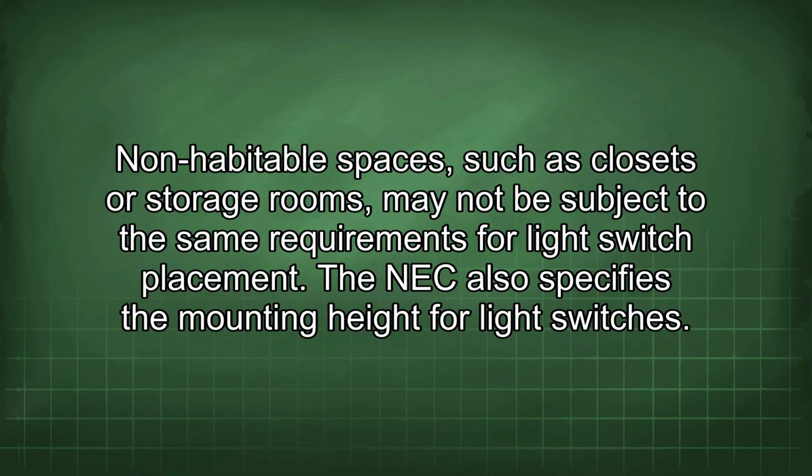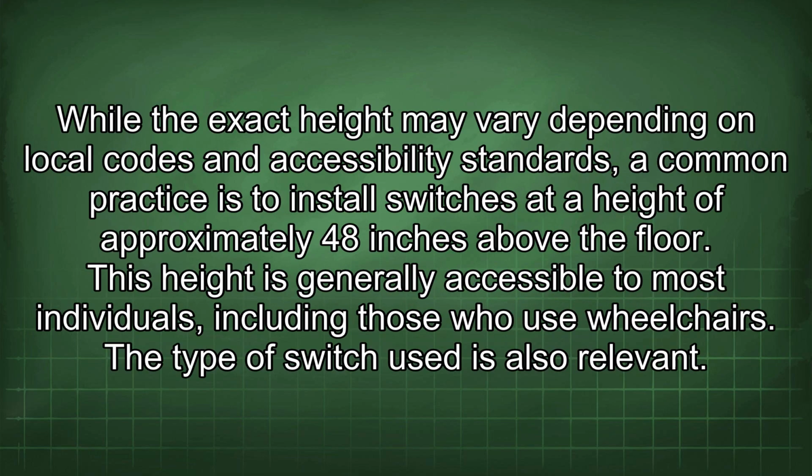The NEC also specifies the mounting height for light switches. While the exact height may vary depending on local codes and accessibility standards, a common practice is to install switches at a height of approximately 48 inches above the floor. This height is generally accessible to most individuals, including those who use wheelchairs.